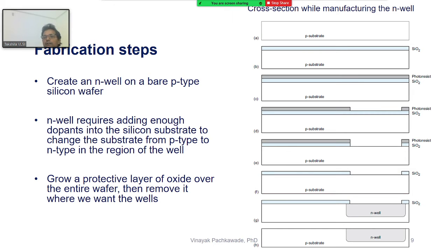So for that, this is also a quick synopsis, giving you an overview about how the basic transistor circuits will be fabricated after you lay them out in your tools and send them for fabrication. It is also important to understand how they will be fabricated. So what you do here, you start with the P substrate. The foundry engineer will do that. They will start with the P substrate.